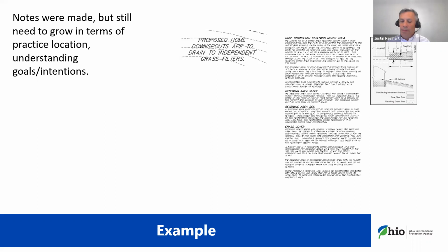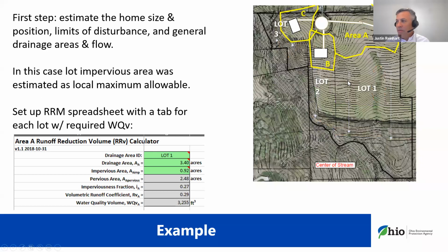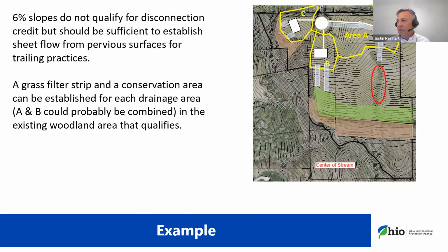But this is probably the challenge, is thinking of this, and I'll go backwards, in terms of a BMP to show you the sketches, and making sure we're identifying these practices, locating them on the plans, assuring that, again, moving backwards here for you, that these are actual areas that will receive the flow, not just circling areas that are high quality but aren't receiving any runoff. So we're attributing only the area receiving runoff from the site, and then including any other drainage area here in that calculation.